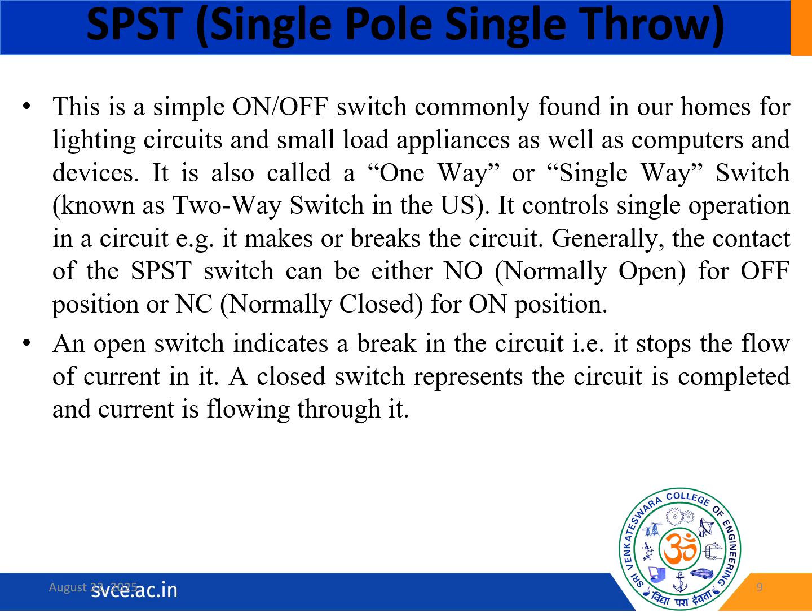So the SPST switch is considered to be a basic on-off control. This switch has one pole, so it controls a single circuit, and one throw connects or disconnects the circuit in a single path. Moving on to the working of this particular switch, consider a basic light switch, with on position and off position. When the contact is closed, it allows current to flow. If the contact is open, then it interrupts the current. That is the normal operation we specify in SPST.